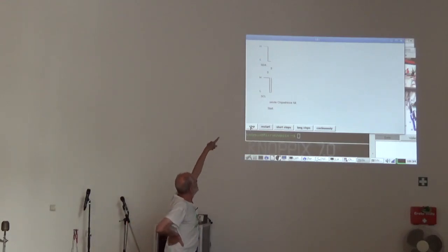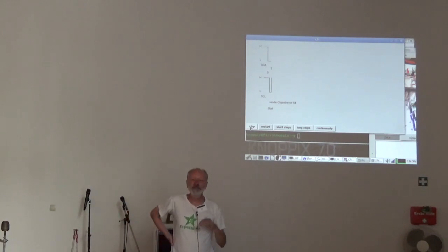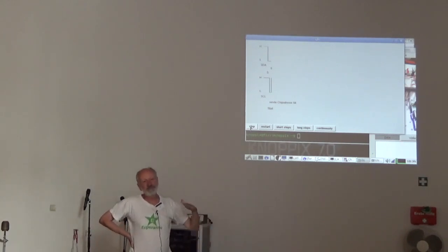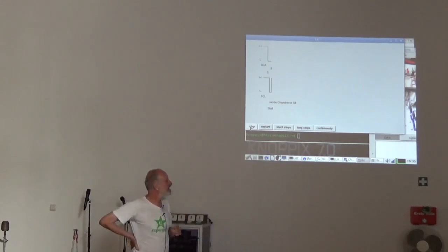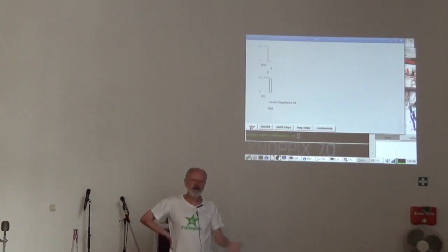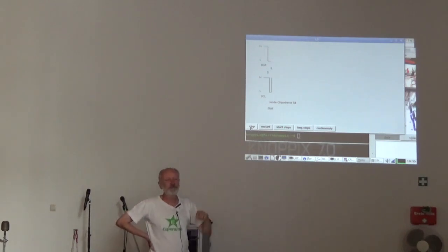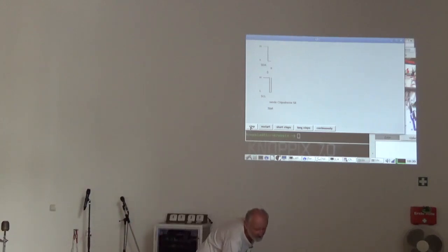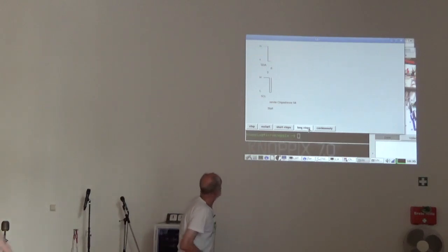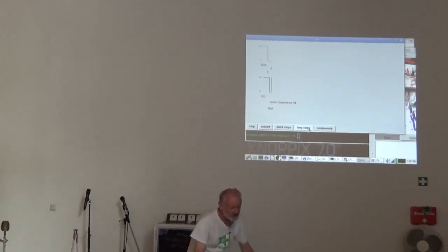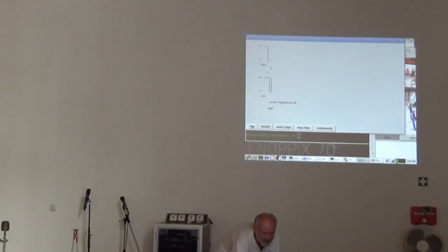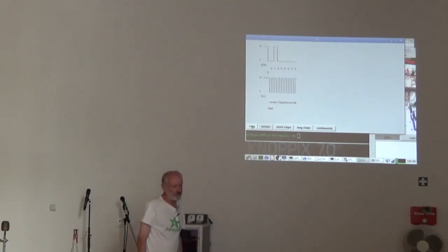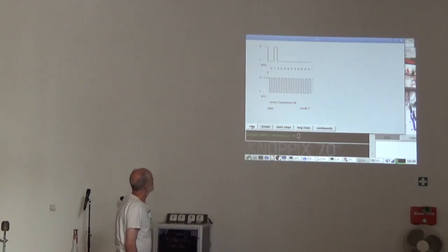When it is low, then the serial data must be set to either 0 or 1. In this case, it is a 0. And when the serial clock rises, then this 0 bit is sent to the chip. And now I make long steps, so I will produce several bits at a time to show how this works.